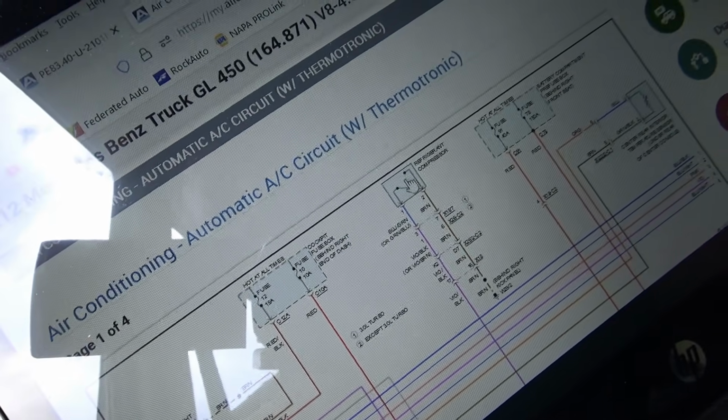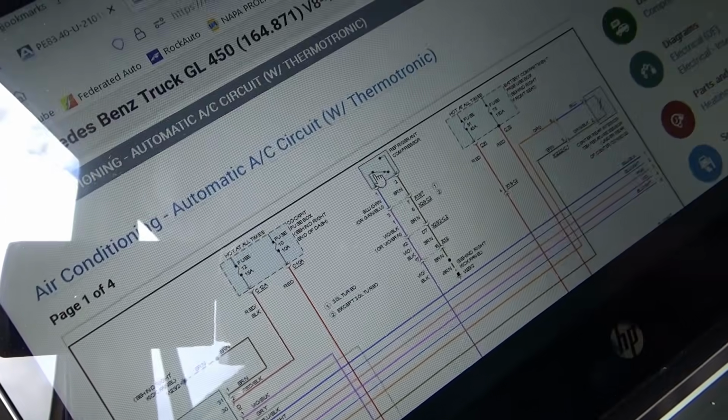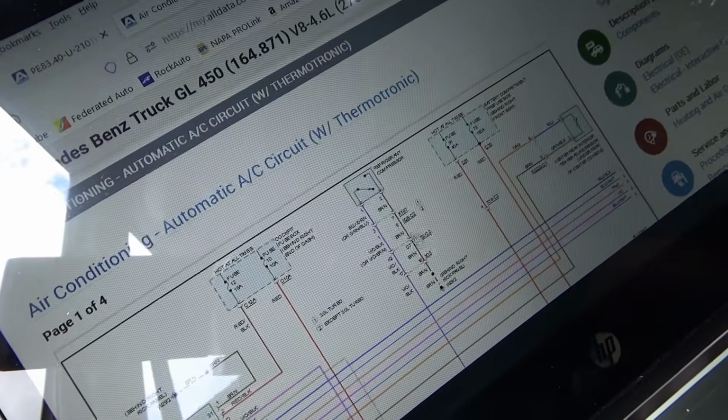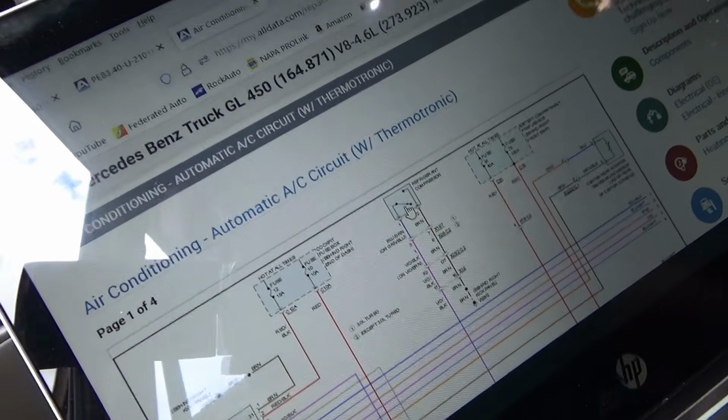It looks like a switch in here, but it's that valve, and this is a variable voltage, and it's just grounded. So pretty simple. The more current goes through here, the more refrigerant is pumped through the compressor. So let's get under the car, get to these wires, and see what the controller is doing on that circuit and why it's not happy.